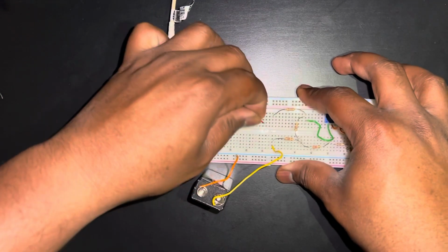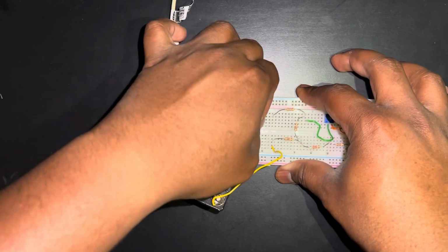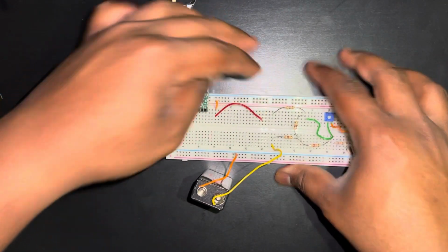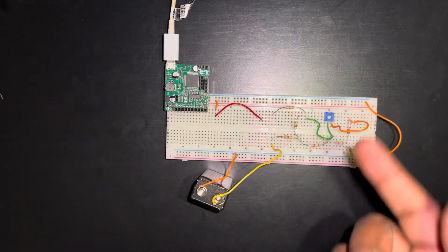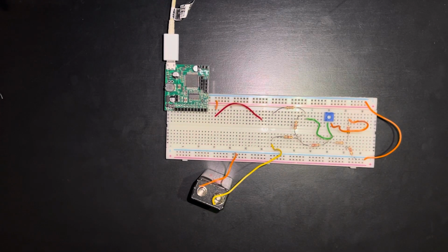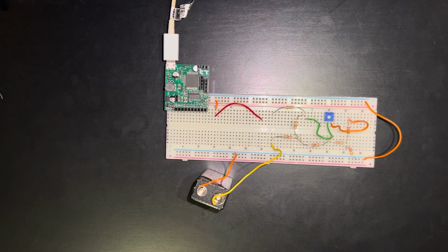In order to do that, you have to make the discontinuity and then measure the current across it, right? So that's how you do it. Make the discontinuity and then measure the current with the help of a multimeter. And then what you have to do is sum the values of the nodes. For example, for the voltage of the nodes 3 and 1, you have to add up the value from figure 1 and figure 2, and then after adding those up, you have to see how much they differ from figure 3 in terms of percentage, and then complete the superposition table.